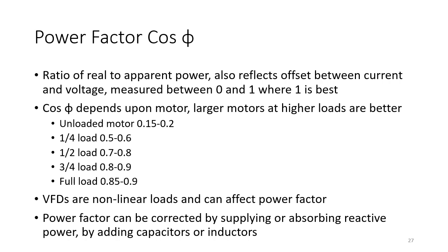So what you might need is to apply that correction on your site by performing some sort of corrective work, adding capacitors or inductors to supply or absorb reactive power, by offsetting reactive loads in one direction against reactive loads in another direction. But also this is why we want to choose the VFDs and the motor to be as close to the required load as possible, because the closer they are to the full load, then the less power factor correction we have to do.